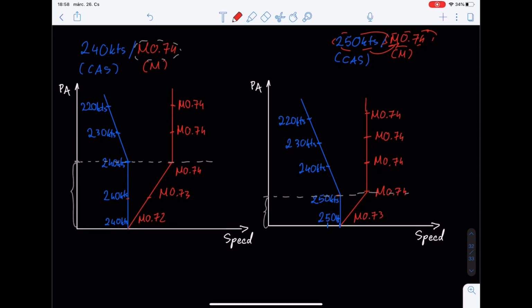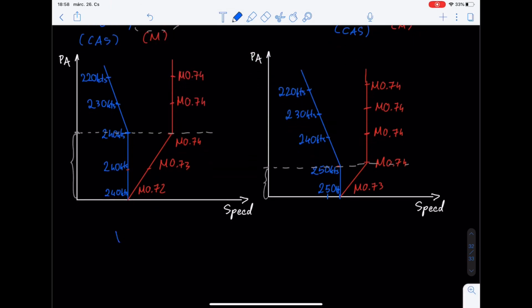So the calibrated speed with which you're going to climb, it would make sense at this point for you to say that, well, initially it is going to be Vx, and then after that we're going to switch over to Vy. Or if we don't have a significant obstacle, we'll just accelerate to Vy straight away, and then we'll just climb with that, because we said that that's the most fuel efficient climbing, right? Because that's what's going to give you the highest rate of climb.